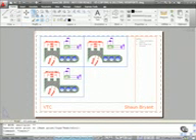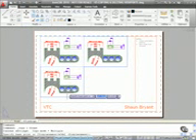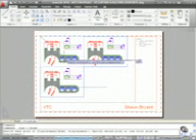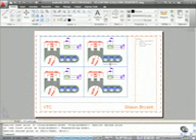So I'm going to go to copy selection here on the modify panel, or I can just select it, right click, and still use copy selection here on the shortcut menu. Either will work. So if I now pick a base point, top left corner again, and drop it there, I've now got 4 viewports. I'll press enter there just to close out the copy command.